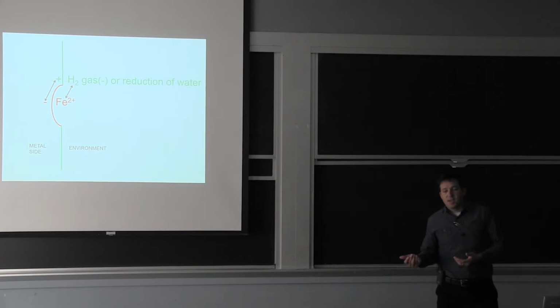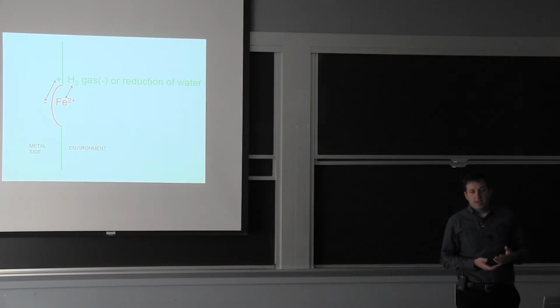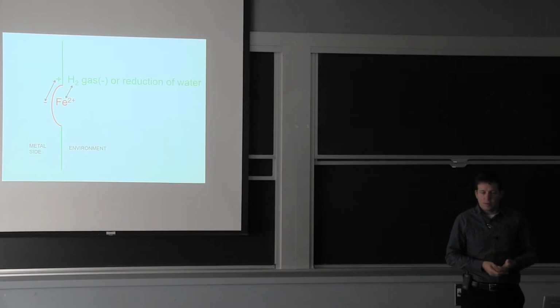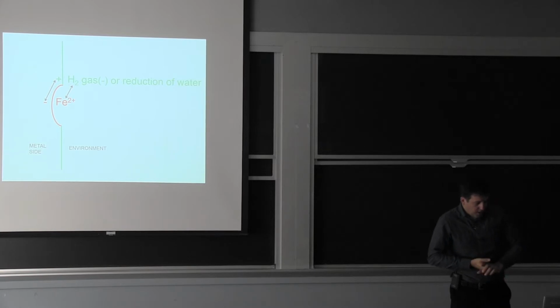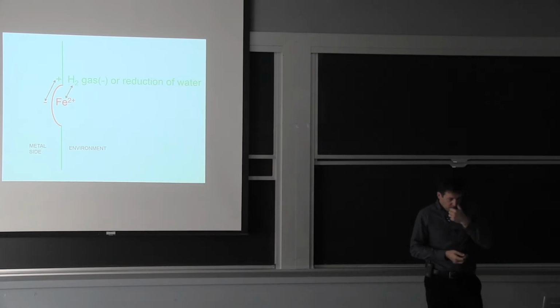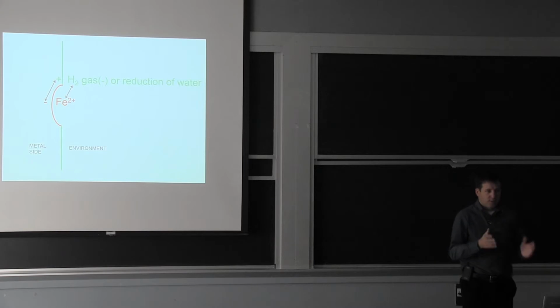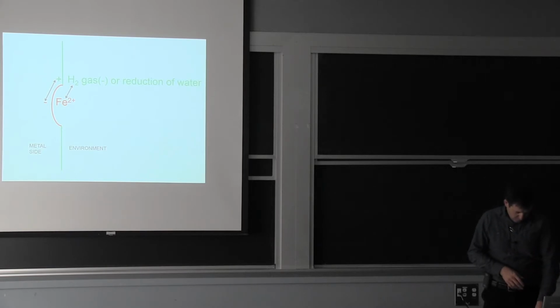What happens on the anode also varies if you're getting 2 levels of oxidation of the iron or 3 levels of oxidation, whether you form a hydrate or you form a more compact compound. And it will vary with temperature, but the basic idea is the same, that even though you start with just one material, it will form these anodes and cathodes on its own surface.